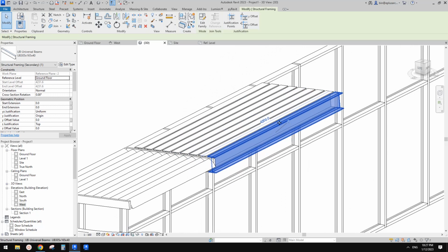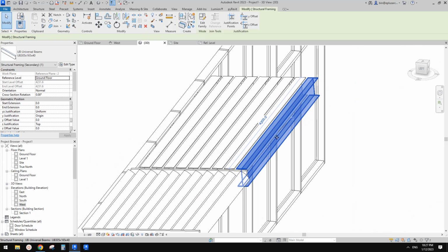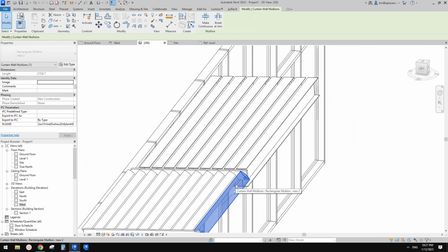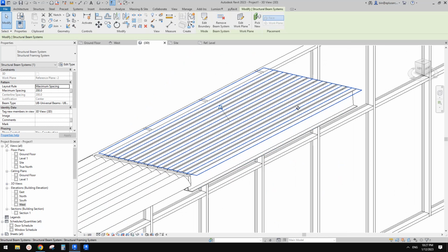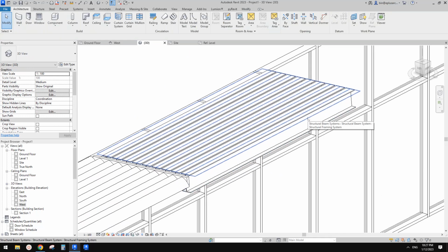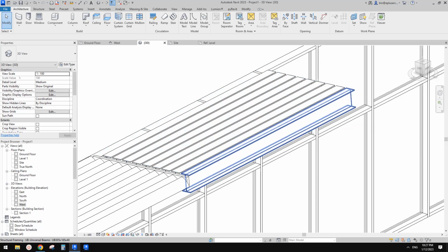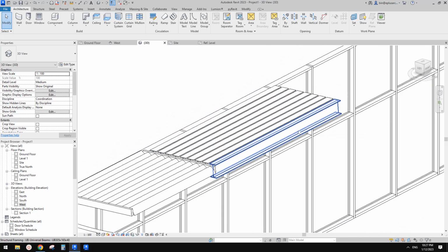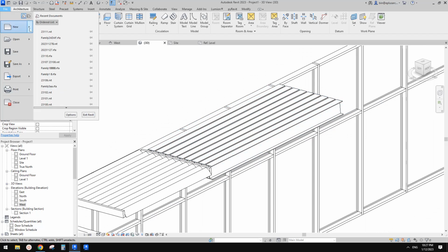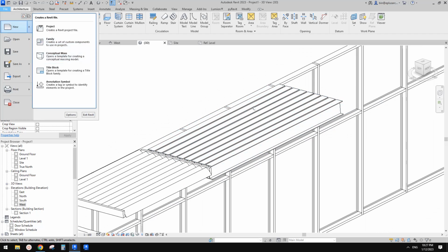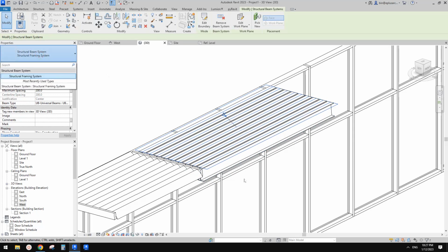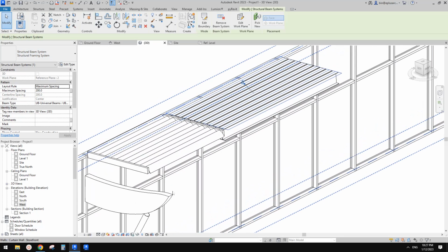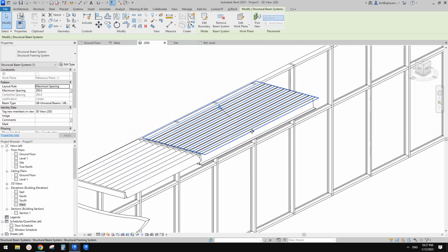Okay, so the issue is we needed to have a beam look like this one. So it looks like we need maybe a custom profile and then create a custom beam. I'm not really sure, actually. Or maybe let's try this. Because we have a column there. Oh, sorry, we can't use column for beam system. We need to use structural framing.